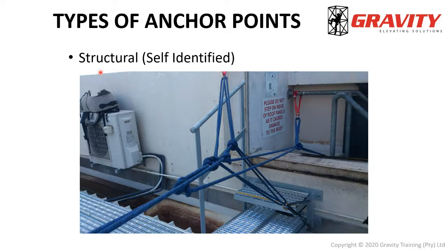Okay, and just a note on the reason why I refer to these as structural. These elements which this guy used to connect his system to are part of a separate structure. They are part of the staircase, or if you are in telecoms, they are part of the lattice mast, or if you're on a mine, it might be part of the gantry, or whatever it may be. These things were installed and erected with another purpose in mind. So they form part of the structure, and they were there for a different reason. Therefore we have to identify whether these anchor points are safe enough or not.